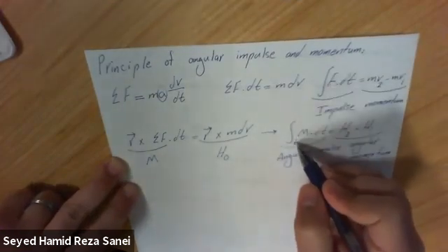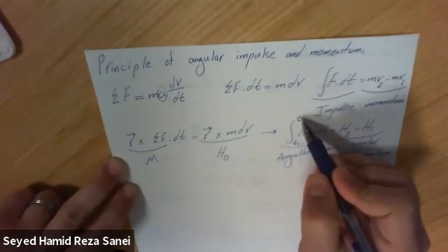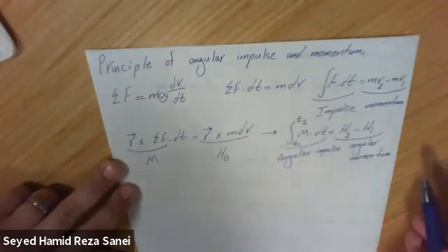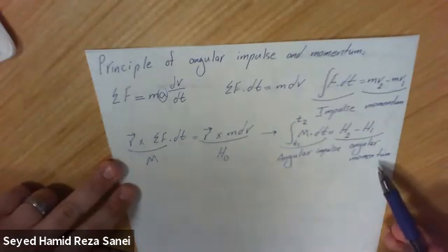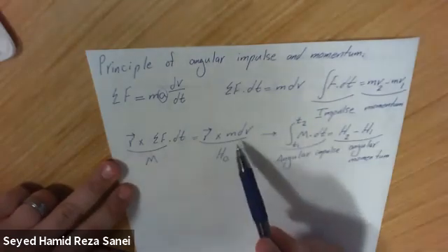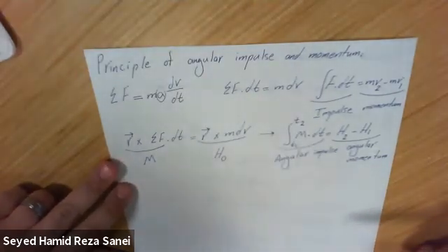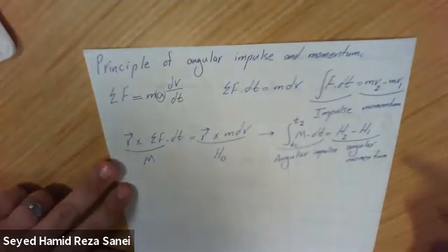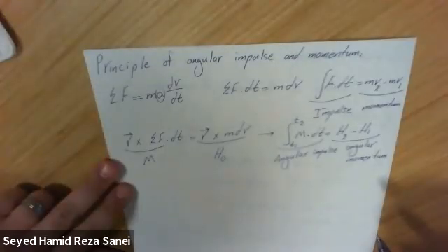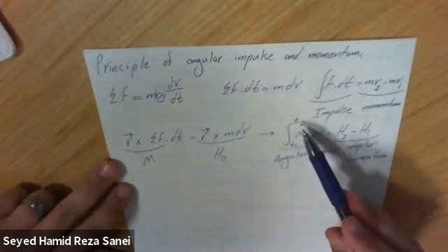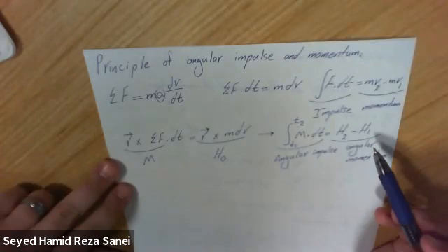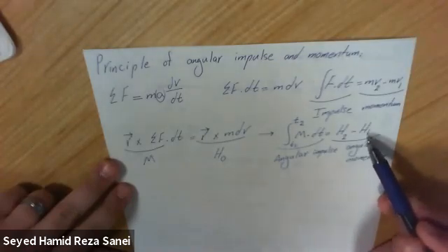Between time t1 and t2. So remember, the angular momentum is the moment of momentum, r cross momentum. So when the angular impulses acting on a particle are all 0 between time interval t1 and t2, when M is 0, then all we have are the angular momentums, the initial and final.